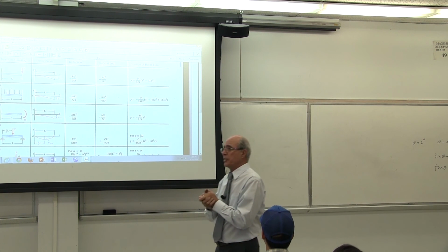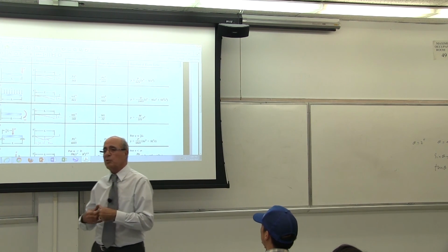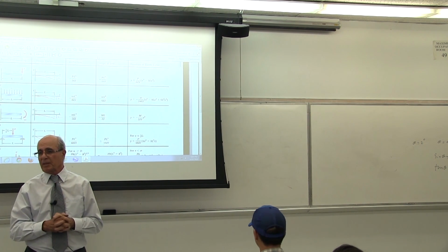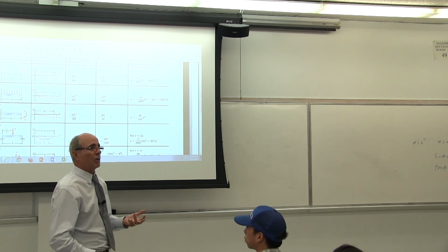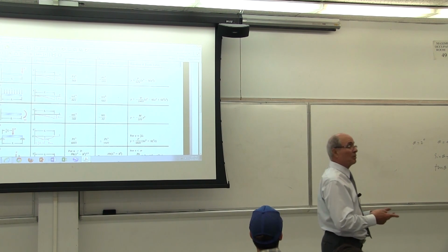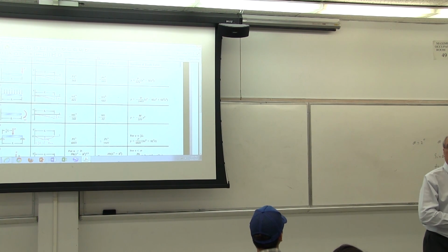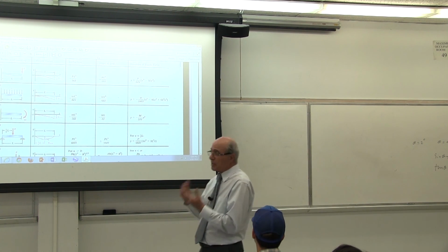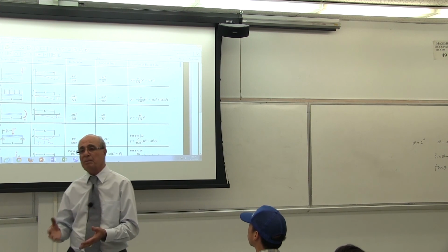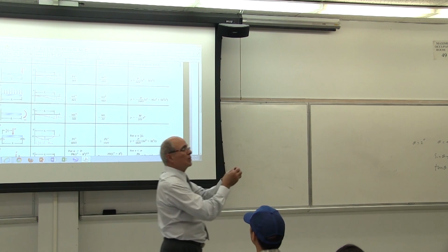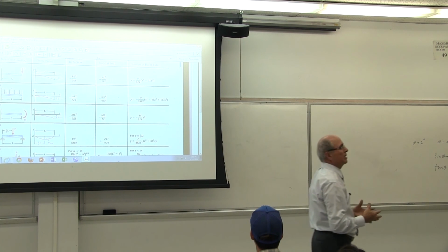When we get the measured strain, we can now go back and check to see what kind of stress is caused by that kind of strain. So we need to draw the Mohr circle for strain. We have to understand what the plane stress is, what the plane strain is, what the absolute maximum strain is, and all of that. All repeat in a way, very simple repeat, with one exception. You have to understand the concept of strain, which is in chapter 1. Is that correct or not?